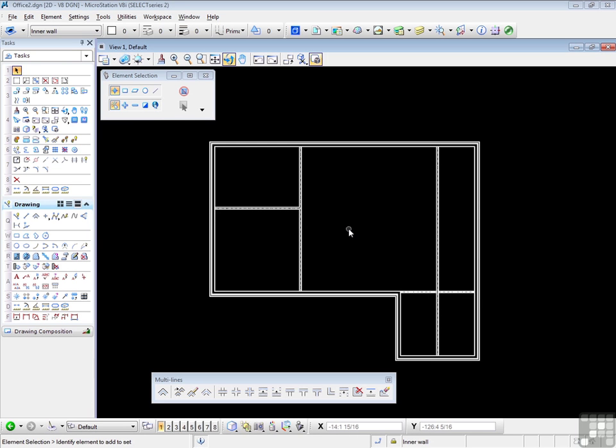Now, it would be nice if the building had an entrance door and some windows. Fortunately, openings in the multilines for doors and windows are easily made using the joint tools. A little care is needed, however, since there are several tools that will cut portions from multilines, and each acts in a different way. Let's take a look at those tools.